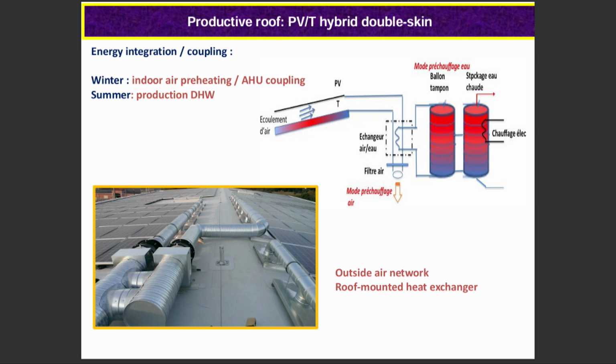And there they use PVT? Yes, we were using this system of PVT winter and summer. But in winter, the collected hot air was directly injected in the building because it was enough to maintain the temperature between 14 and 18. Okay, preheat, but it was enough. And during summer, the hot air was oriented to a heat exchanger with water, which is not so common, to use air to heat the water.